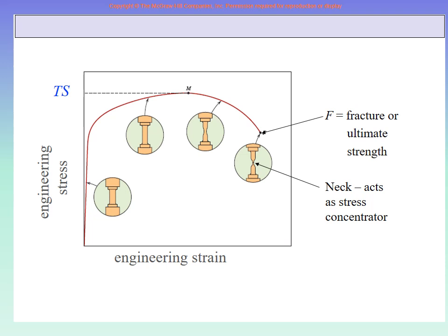We are showing you a typical stress strain diagram for a general standard metal like steels. On the vertical axis is the stress, on the horizontal axis is the strain, and these are the engineering stress and engineering strain, because we are dividing by the original area or the original length. Why do we call it a schematic diagram? Because we are not showing you actual values of stress or strain or the dimensions of the specimen. So this is a schematic stress strain diagram, but it is a very good diagram to give you the typical behavior of a stress strain for any standard metal.